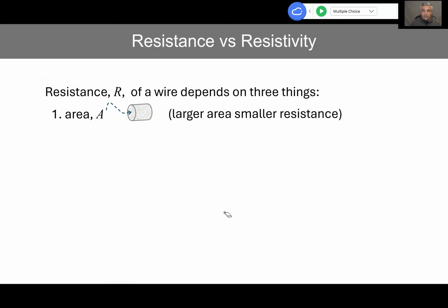So now, although I said resistance is a property of material, what happens is resistance depends on what kind of material it is, and if the wire is longer, the resistance becomes larger. But if the area is larger, then resistance becomes smaller. Let's say we have this kind of big, wide, large diameter wire. So there are going to be a lot of electrons, and more room for streamlined flow.